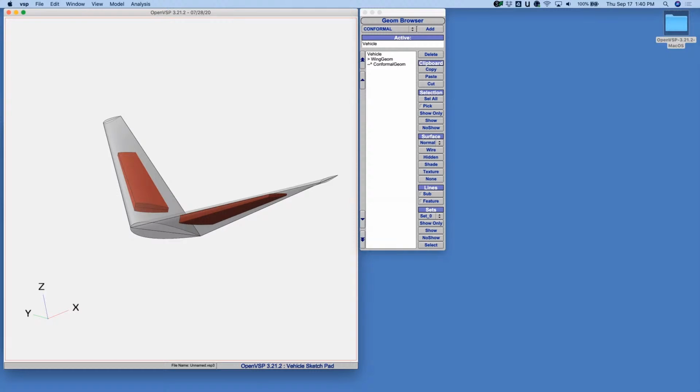Okay, so we've got a question about how to use Fit Model to fit an airfoil from a scanned wing or propeller, if it is possible. Thank you. So what I'd really suggest, if you're trying to fit a full wing or a prop from a laser scan, is to worry about the airfoil last. What you're going to want to start with is getting the leading edge and the trailing edge correct, and getting the planform right, and getting that shape.